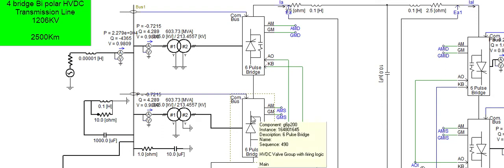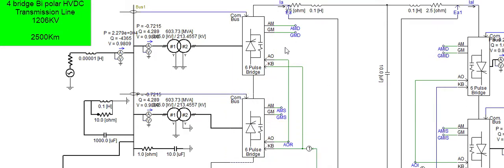Okay, now basic circuit we covered. We developed a diode circuit, we developed a SCR circuit, then we go beyond this and we make several bridge circuits. And before this exercise, as you knew, we completed one small HVDC circuit of around 300 kilometer at 250 kV. As I told you earlier, below 200 kV AC is economical as compared to the DC, because the complete cost of DC is raised up due to these electronic circuitry, this DC circuitry, converter and